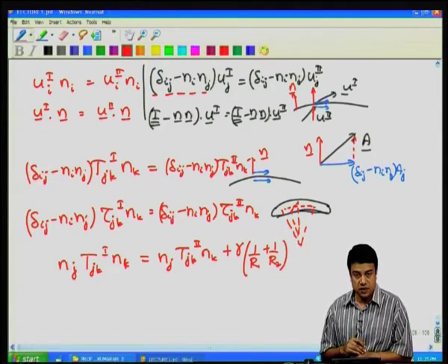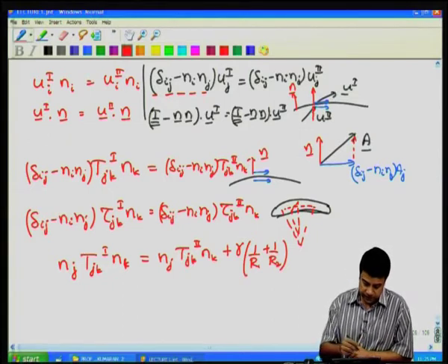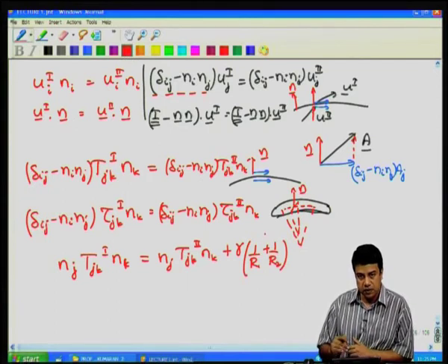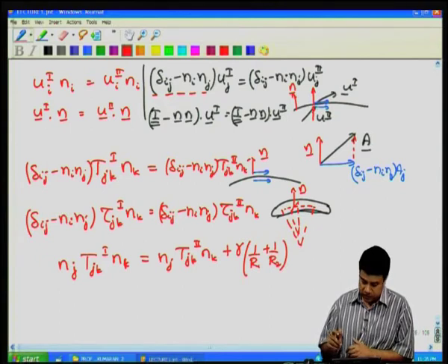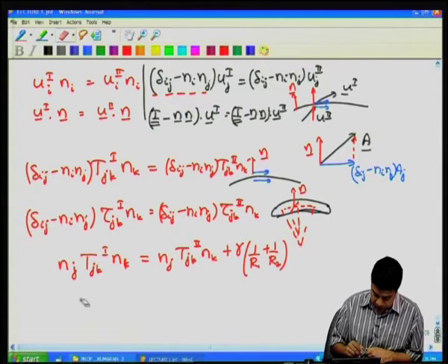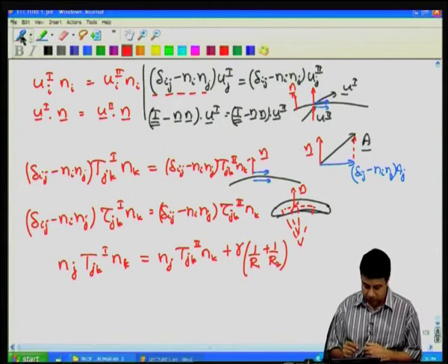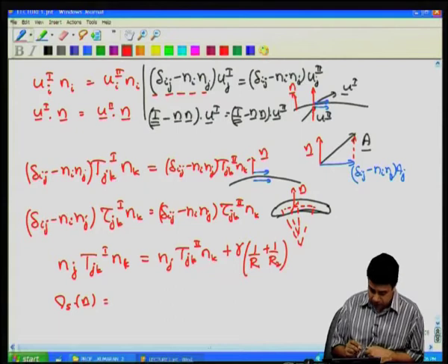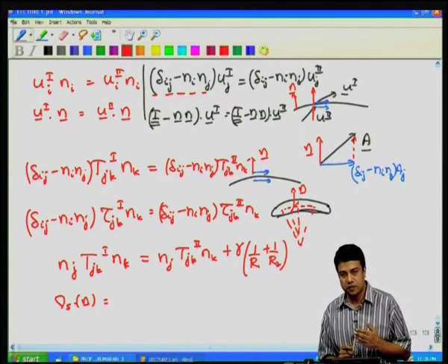This difference in stress can also in general be written in terms of the divergence of the unit normal. If I have a unit normal n that is perpendicular to the surface, I can take the surface divergence del_s of n, which is equal to the divergence of the unit normal along two orthogonal directions along the surface itself.